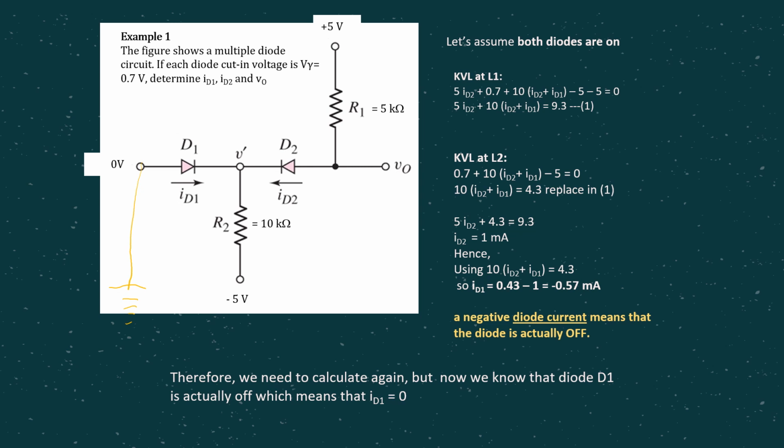How about this one? We have negative 5, meaning this node is connected to negative, while the positive one is grounded. Okay, then as you can see here, ground and ground are at the same level, right? So you can connect them together. Then for this negative 5, because the negative polarity is already represented here, the value of this DC source will be equal to 5 volt only. Why 5? Because negative is already represented with this negative polarity.